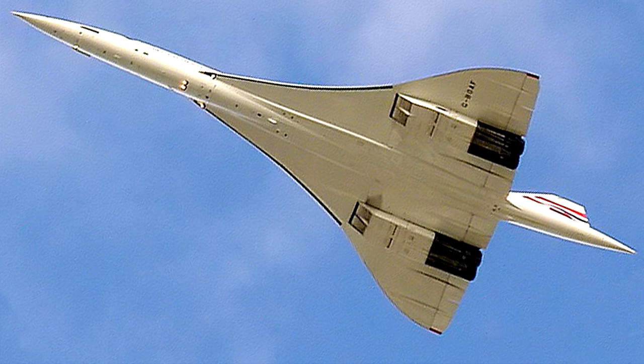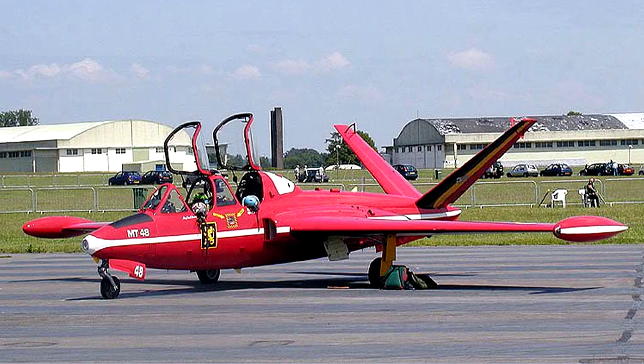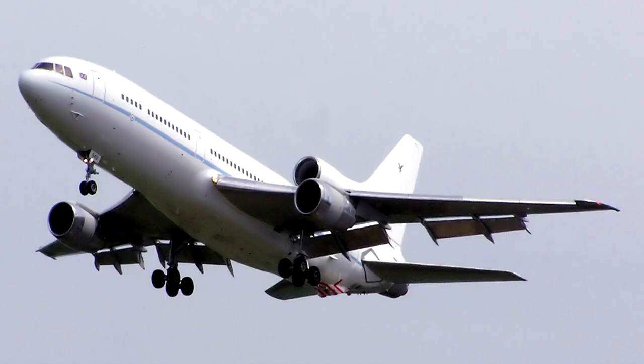On some types of aircraft, rotation around two of the axes may be achieved with one control surface. For instance, the elevon, a combined elevator and aileron, is used on tailless aircraft to give both pitching and rolling control. The ruddervator is the name of the control surfaces on the empennage of a V-tail aircraft, which combines both pitching and yawing control. The stabilator is a movable tailplane, combining the functions of horizontal stabilizer and elevator. One of the few airliners to use a genuine stabilator was the Lockheed TriStar.